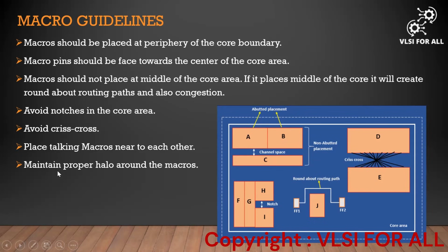And the last step is to maintain proper halo around the macro. Around the macro, we have to maintain some proper halo area, which means some kind of partial blockage, and we can place it around the macros.